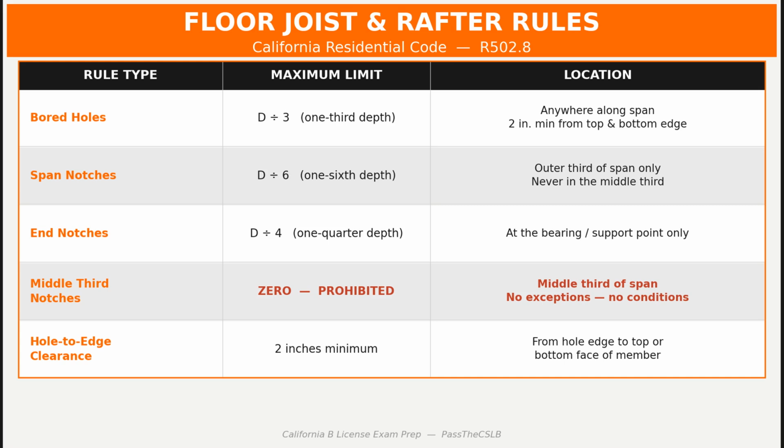Vertical wall studs operate on completely different mechanics. A bearing wall stud is a column in compression. It carries the cumulative weight of everything above it and transmits that load downward. Columns fail by buckling, and buckling is not a gradual process. A column holds its full load until the instant it does not.